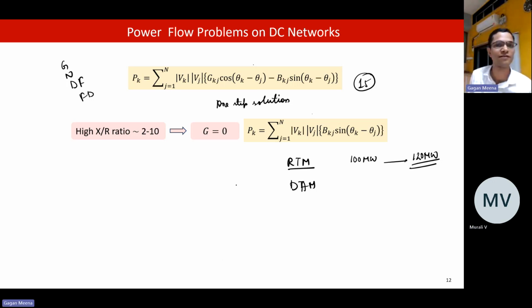Because the network operator always keeps an eye on the network, he always has a margin on the power flow. So whatever generation schedule comes out of the bid matching algorithm, the operator will try to run his own power flow and match it. Because there are certain margins, he can handle things. Whenever a quick solution is required, we use power flow.